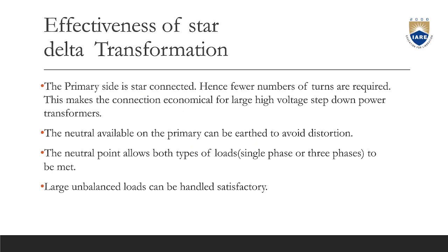Effectiveness of star delta transformation. The primary side is star connected, hence fewer numbers of turns are required. This makes the connection economical for large high voltage step down power transformers. The neutral available on the primary can be earthed to avoid distortion. The neutral point allows both types of loads, single phase or three phase, to be met. Large unbalanced loads can be handled satisfactorily.